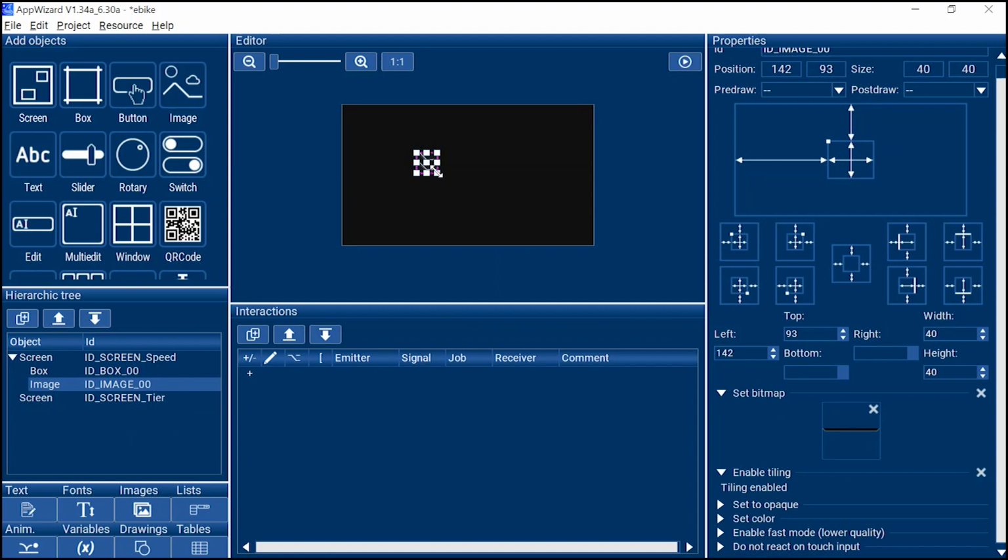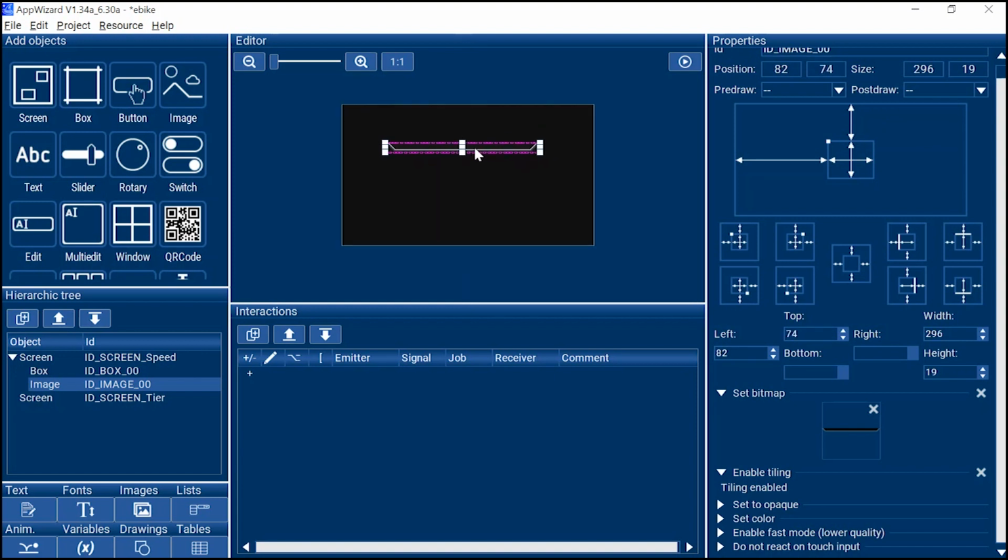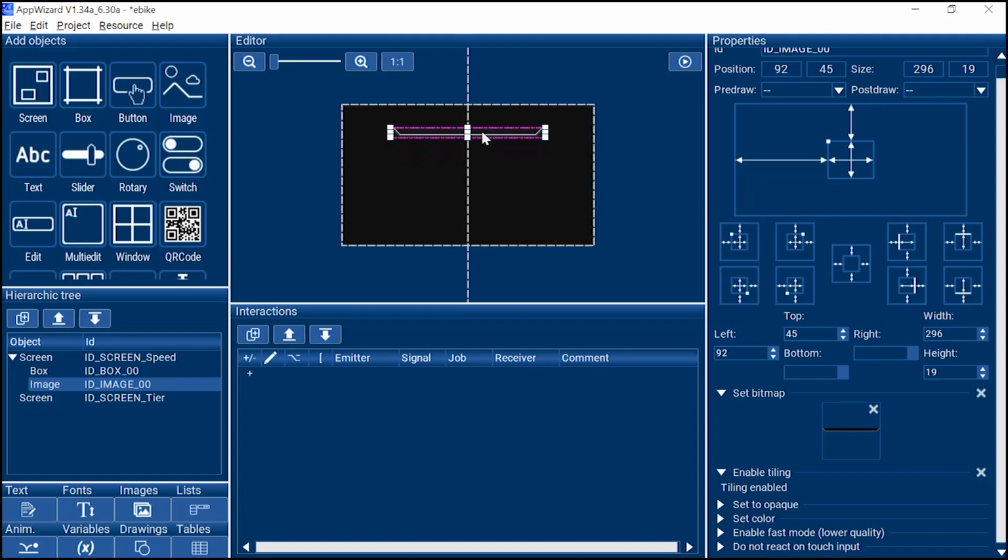The current size may not be suitable, so you can right-click on the image in the layout and choose Set Size to Content. It will automatically adjust the size to fit and display it in the layout. Then you can use dragging and alignment to position it on the grid where you want it.